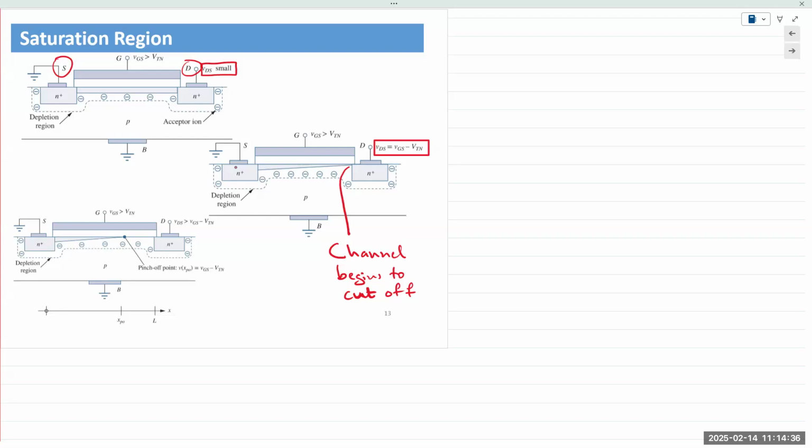So what happens to the current flow? In a FET, when the channel pinches off, what happens to the current flow? The current remains constant. In terms of physics, what happens to the electrons or charge carriers that are present in the channel? We say the channel is pinched off, but electrons are still injected, and a similar effect takes place here.